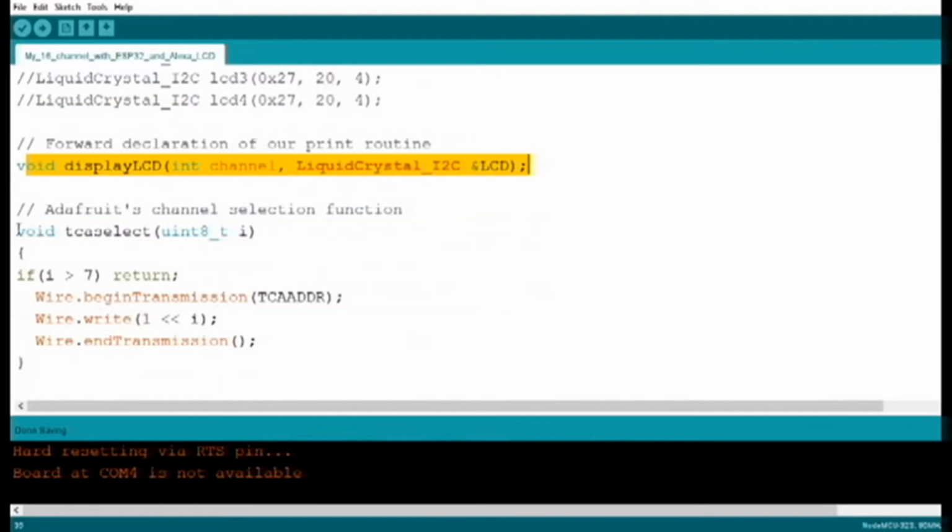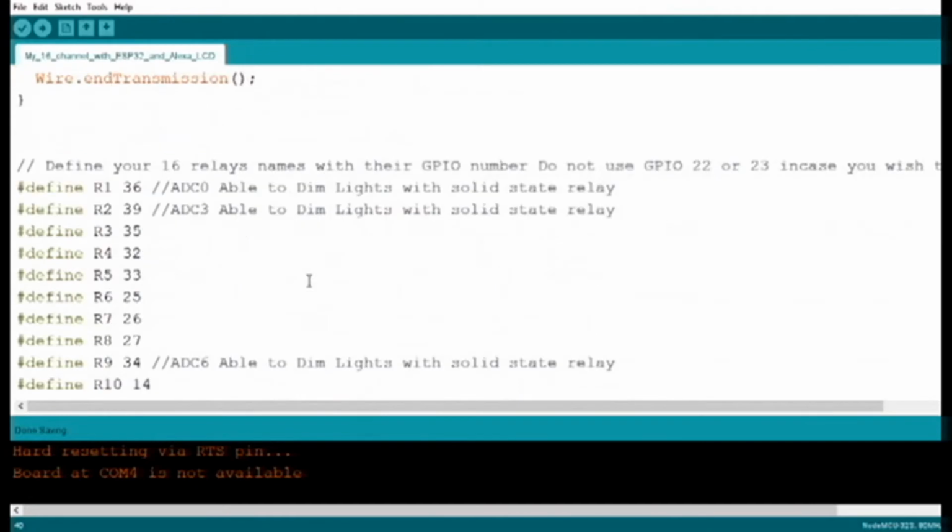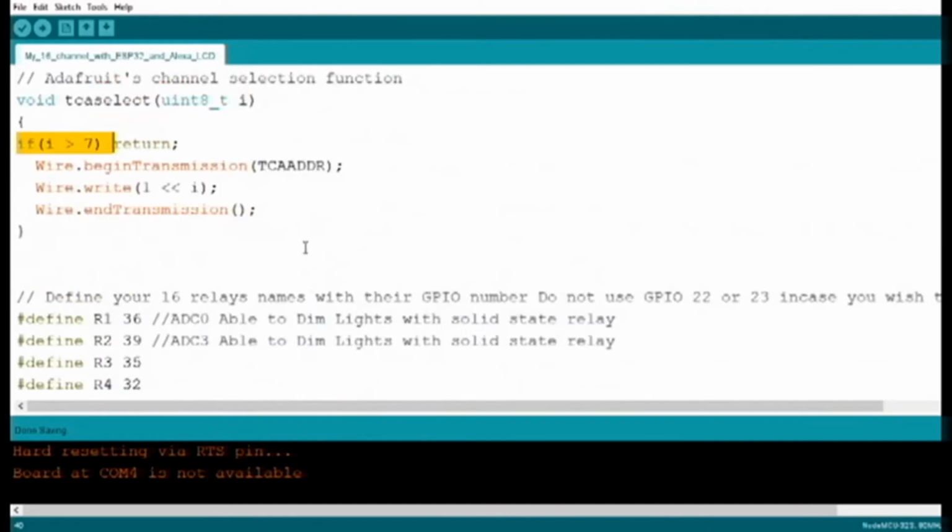On the other hand, here is where we are setting the multiplexer's channel, and how we call each channel. This line you want to set to the number of channels you are using, or are planning to use. At this time we don't know how many channels we will need by the time we are done, so we set it to use all 8. Note, the channel numbers start at 0 and end at 7.